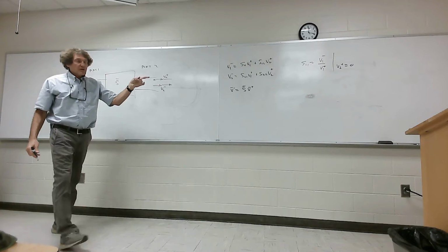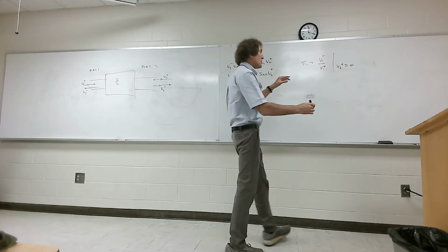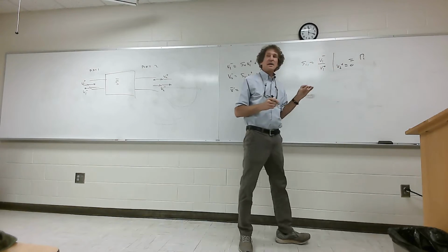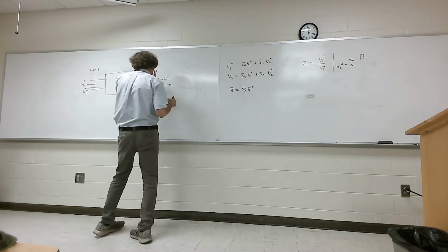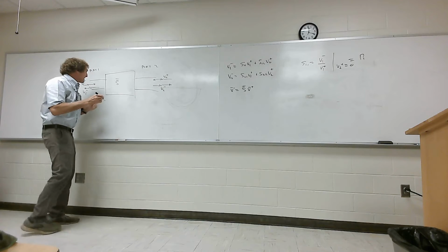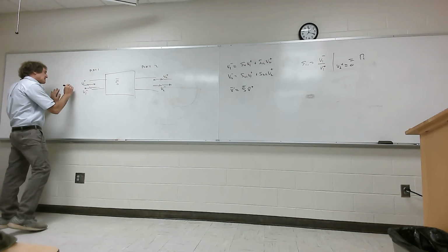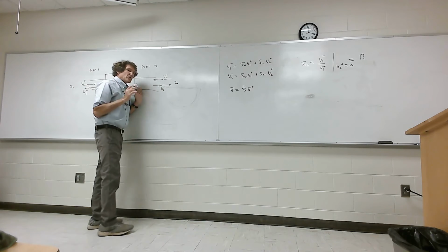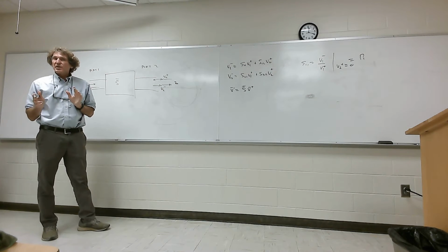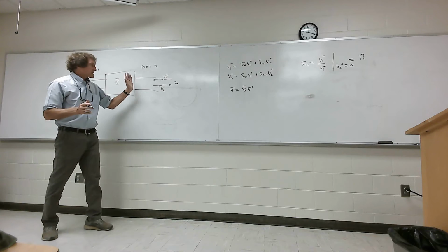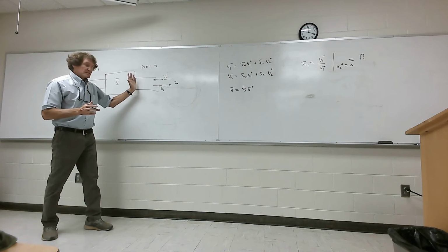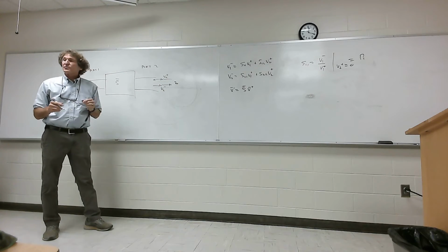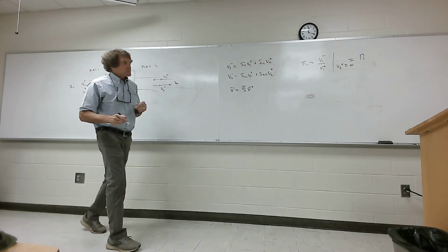So that is the reflection coefficient, and you can even put it as simply the reflection coefficient of port 1, assuming that out here we have what's called a match condition. Now, I didn't put this down there, but it's assuming the lines here have a characteristic impedance, and this is Z naught here. So really, when we say V2 plus is 0, it means that the signal, once it goes through this port system, is coming out, there's no reflections. It's matched over here. Right? That's what it really means. So that's what S11 is.